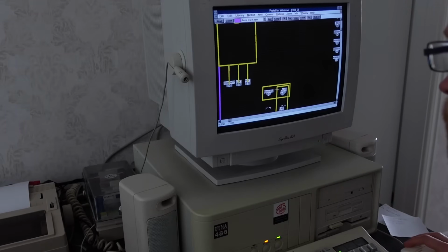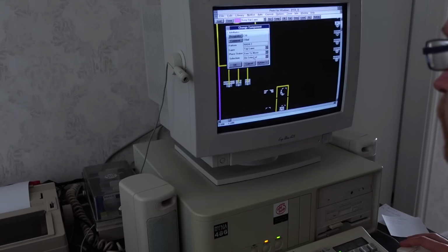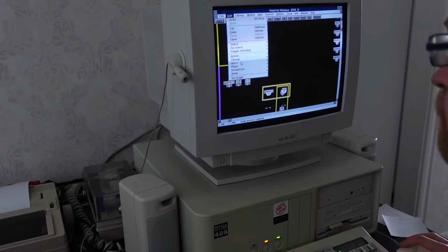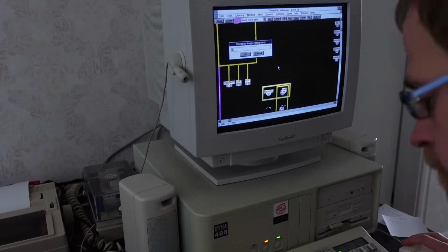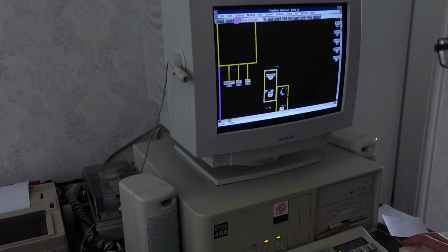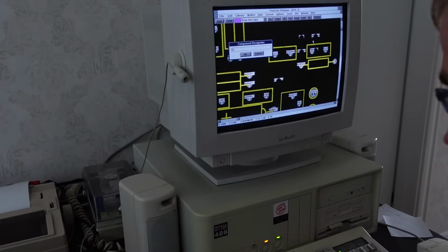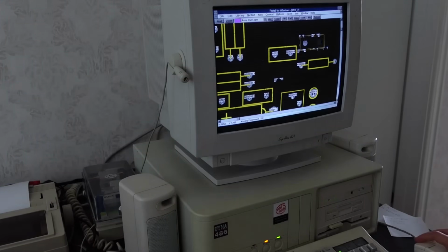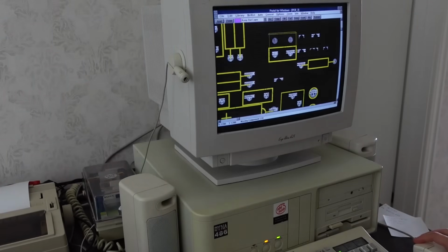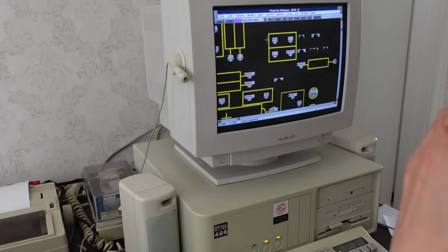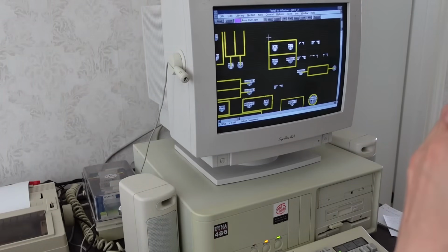Just to rotate a component without keyboard shortcuts, you have to select the component, then go into the menu to select rotate, type in the angle. Rotations are done counterclockwise. Moving components is best done by clicking on an empty space and typing in the reference designator. Otherwise, you might not always grab the component by pin 1, which can screw up the alignment.